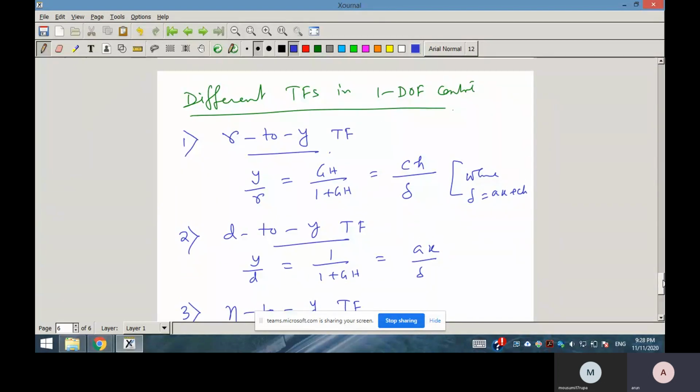This limitation has to be avoided because delta S is in your hand. You will choose delta S as you want, but you do not know what the HS and KS will be. If their roots are near the imaginary axis, your performance ultimately will be poor, even though you have placed the poles at desired locations.